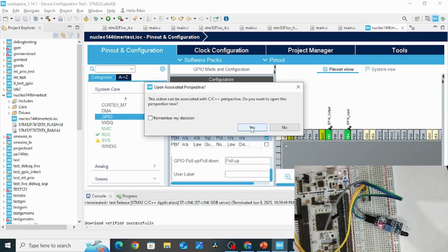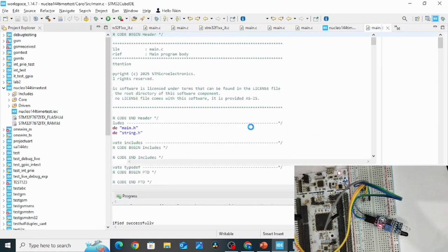So now whenever this proximity sensor detects something, it will write into this controller, STM32. STM32 will observe this. It will start the counter using interrupt. After a certain amount of count, it will generate the interrupt. The interrupt subroutine will be called, and the interrupt subroutine will take the required action. Okay, and this will be parallel with our ongoing task. So this is the overall picture.